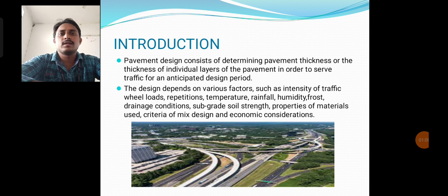If the soil subgrade is weak, which means the CBR value is low, then the pavement thickness will be more. If the CBR value is within the range, then the pavement thickness is less. So pavement design consists mainly of determining the pavement thickness or the thickness of individual layers.